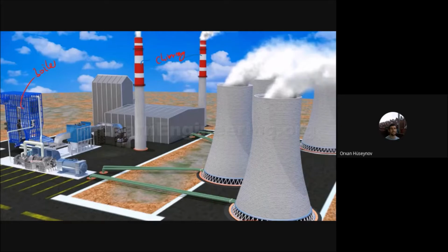From the boiler, the steam comes into the turbine. These are the turbines, and from the turbine you have the generator here, where you get the electricity. Then back here are the filters. These are filtering the dangerous gases from the flue gases, because when you are burning coke, natural gas or fuel oil, you have dangerous gases leaving the combustion process. And here we have this filter system, precipitator, collector system, etc.